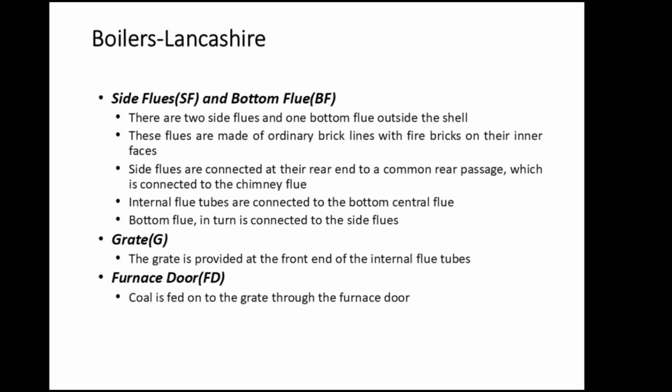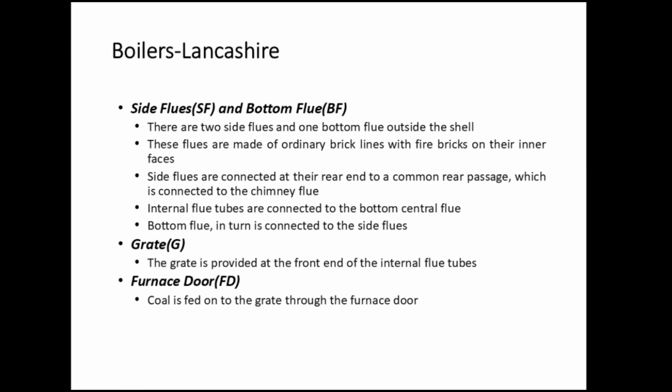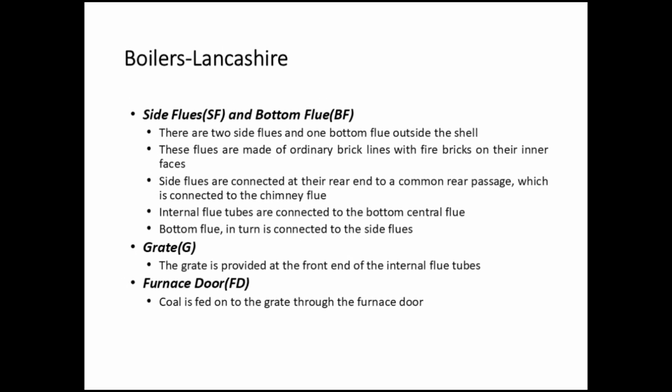Boilers, Lancashire, side flues and bottom flue. There are two side flues and one bottom flue outside the shell. These flues are made of ordinary brick lined with fire bricks on their inner faces. Side flues are connected at the rear end to a common rear passage which is connected to the chimney flue. Internal flue tubes are connected to the bottom central flue. Bottom flue in turn is connected to the side flues.